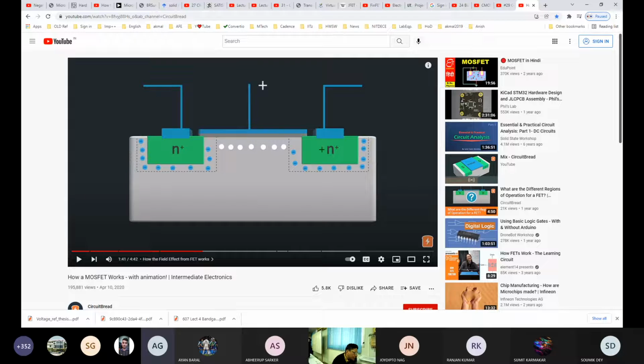Here we have, this is the source, this is the drain. When the gate voltage is 0, there is no connection, as has been explained. And what we do when we apply a positive voltage, the positive voltage repels the holes from the P substrate, or this is the body. Between the source and drain is an area called the channel region, this time a physical region. The channel region means the separation between the edges of source and drain. And this is a very important parameter that's called channel length, L.